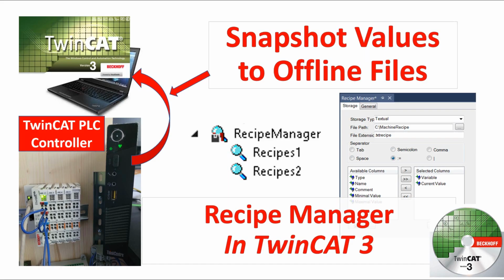Hello everyone, in this video I'd like to talk about how, in the Beckhoff TwinCAT 3 system, we can snapshot the PLC online values to an offline file. This is a very important feature to allow us to capture or snapshot all the important set points or some important recipe values to an offline file so we can review the values offline.